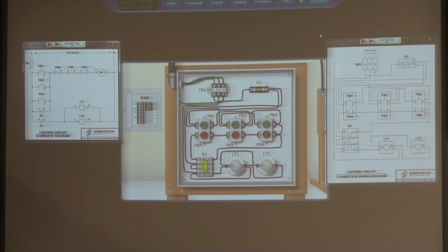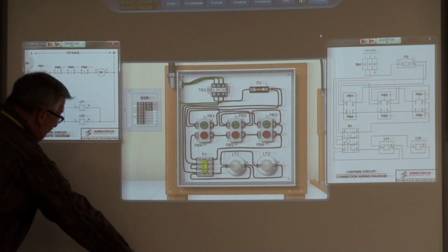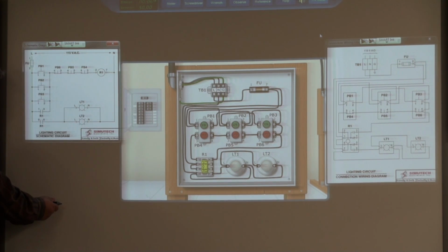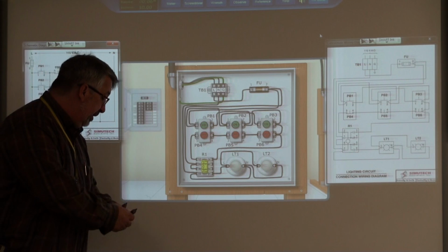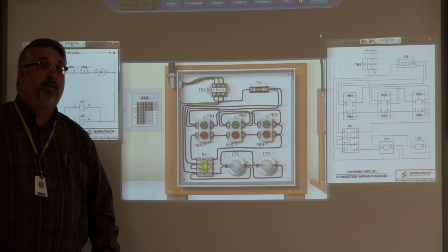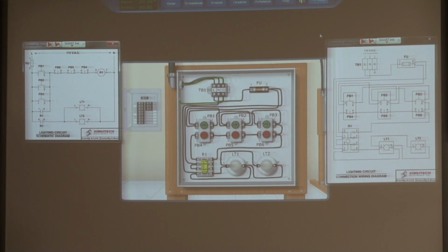That's a good point. If this is the back of the cabinet and this is the wire, and we have a break like that, then it wouldn't necessarily blow the fuse. But if during that vibration the hot side touched that cabinet, then boom, we've got a problem. You can also have a broken wire where the insulation isn't broken. The wire could be broken inside, or it could be nicked, but not broken in two. Exactly right.